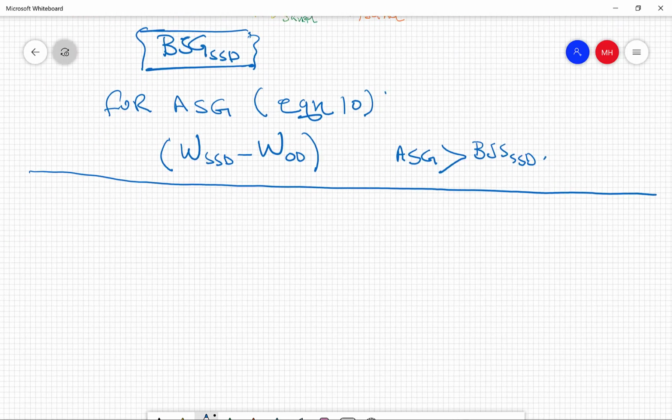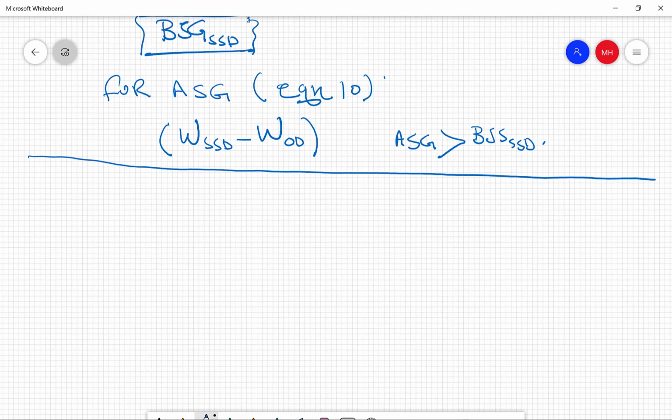So let's talk now about the measurement of the moisture content. The measurement of the moisture contents of aggregates can conveniently be made using the displacement methods used for the determination of the bulk specific gravity in the saturated surface dry condition. So basically, using bulk specific gravity methods.